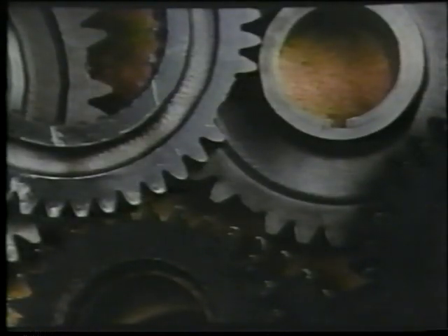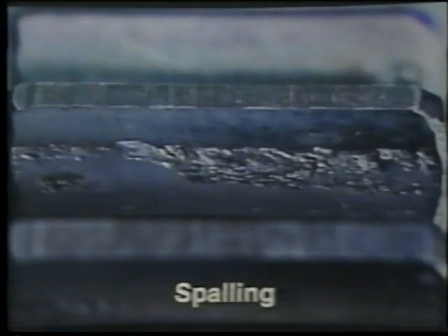We've looked at examples of minor and progressive forms of gear tooth surface distress, problems that may not require replacing the gears. Now let's examine the kinds of trouble that always require replacement, replacing not just the single distressed gear, but the gears it mates with as well. This is spalling. Extreme overloading for a short period of time can cause these craters, which are similar to destructive pitting, except that the pits are wider and shallower. This gear and its mates should all be replaced.